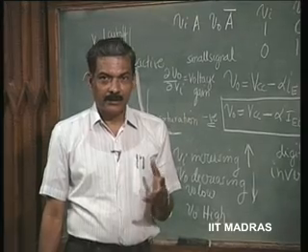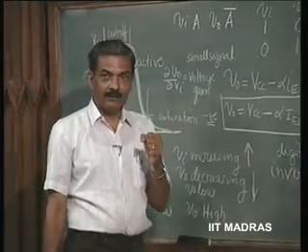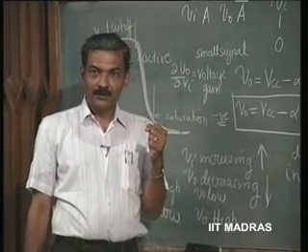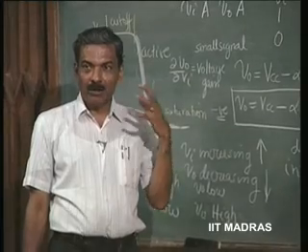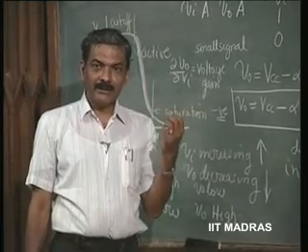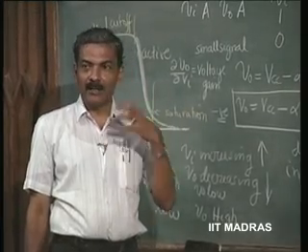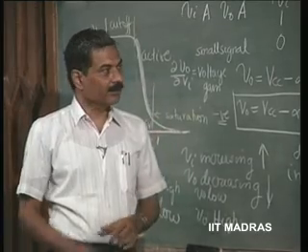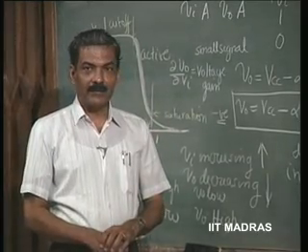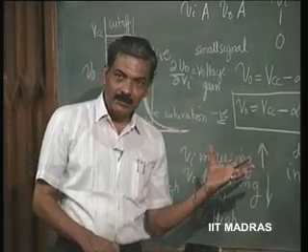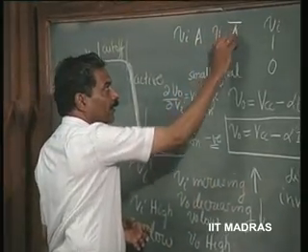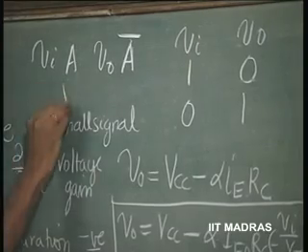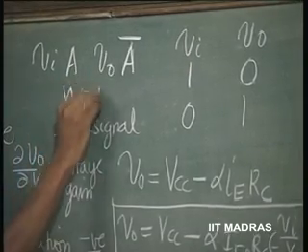What we have learnt with diodes, the diode gate, we discussed the AND gate and OR gate. By using just diodes, we can build AND gate and OR gate. We had seen this logic when we discussed applications of diode. Now, adding this operation, where A is input and A bar is the output, is a NOT operation.